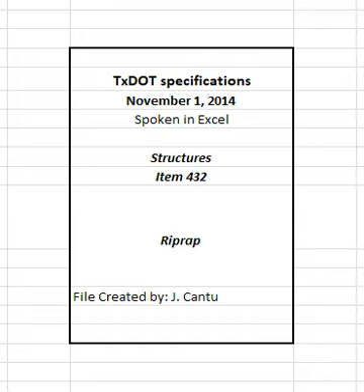2.4 Cement stabilized riprap. Provide aggregate that meets Item 247, flexible base, for the type and grade shown on the plans. Use cement stabilized riprap with 7% hydraulic cement by dry weight of the aggregate.